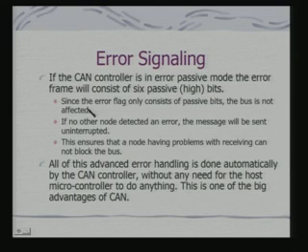A node may find it is getting into repeated error. This is because, if you remember, a node goes into passive error mode when there are more frequent errors and when it is not in a normal mode of operation. So, that means the error that it is detecting may be because of a malfunctioning of the CAN controller at that node itself. So, effectively what is it pushing now? It is pushing 6 passive bits, and these bits will not modify the data on the bus because the low bit is the dominant bit. Is this clear? So, data transmission will take place without any interruption. Only the current node will be unable to receive the data.